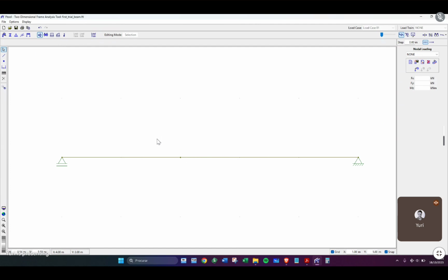For this video only, let's just apply a nodal force in here. To create this, just like the other parts, you click a new one. I'll just call it P equals 5 kilonewtons. I'll click done. And here you can apply 5 kilonewtons in the bidirectional axis and also moment. Since we're just creating a load, I will apply a -5. And I will select the nodes and apply, right?